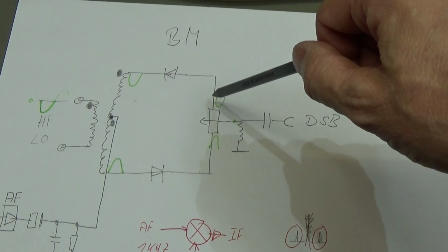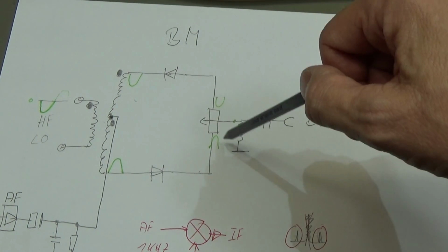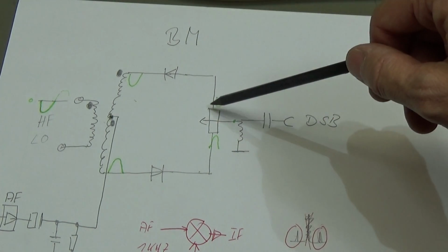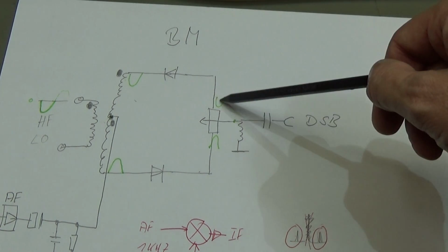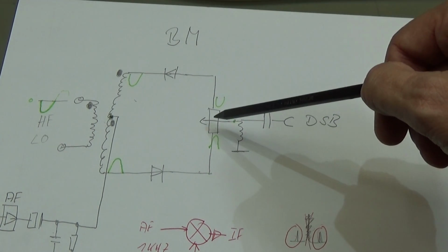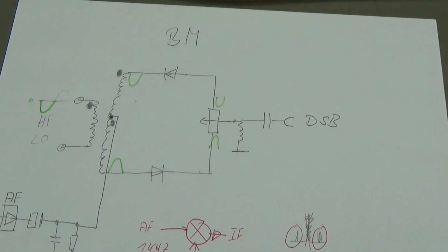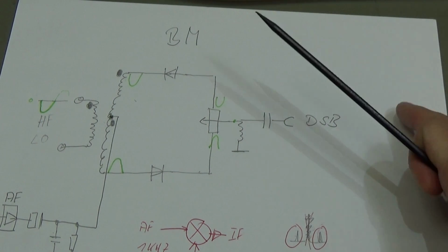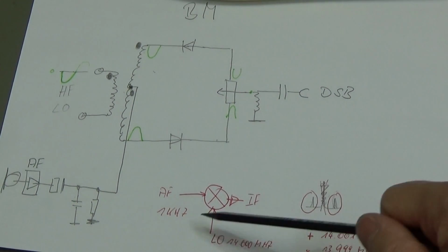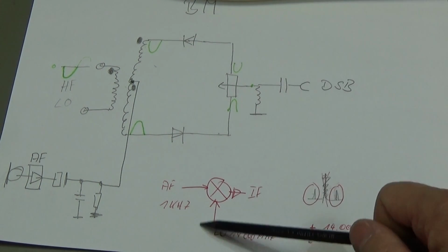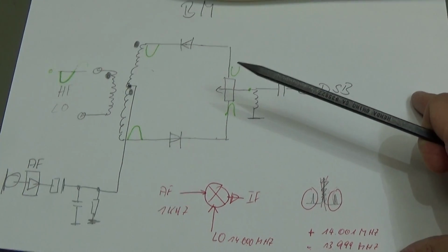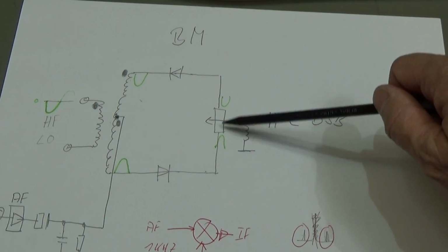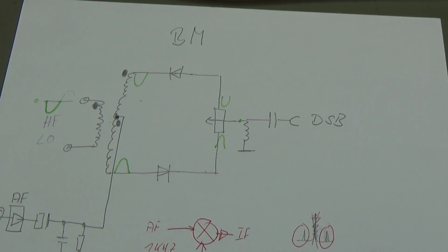We really have a positive half wave and a negative half wave here at our resistor, and both get summed up, and as they have a phase shift of 180 degrees, that means that our 14 megahertz, which we are feeding in here in our example, will be reduced to nearly 0, and that is what will happen.